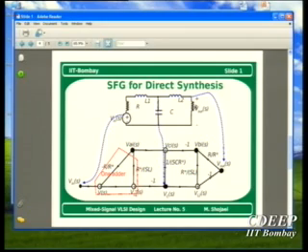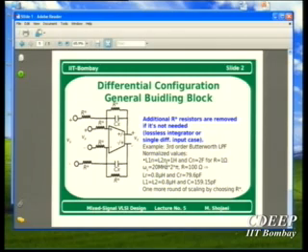First of all, you can imagine you have negative values of resistor or capacitor. Therefore, you can simply use a single-ended version of this implementation and convert it to differential mode. So the component we use for differential mode is essentially a differential in, differential out op-amp. In general, we use this type of module. It's a lossy integrator with two inputs.